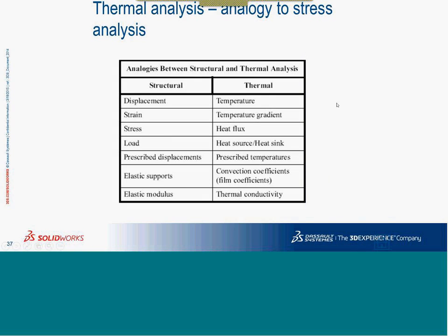So, thermal analysis analogy for stress. This interesting fact has been highlighted in the textbook, wherein we say there is an analogy between a stress analysis setup and a thermal setup. If you observe, displacement is similar to temperature. That is one of the basic quantities. Strain is more like temperature gradient, which is the variation of temperature across a particular length. Stress is per unit area, and over here it is heat flow rate per unit area.